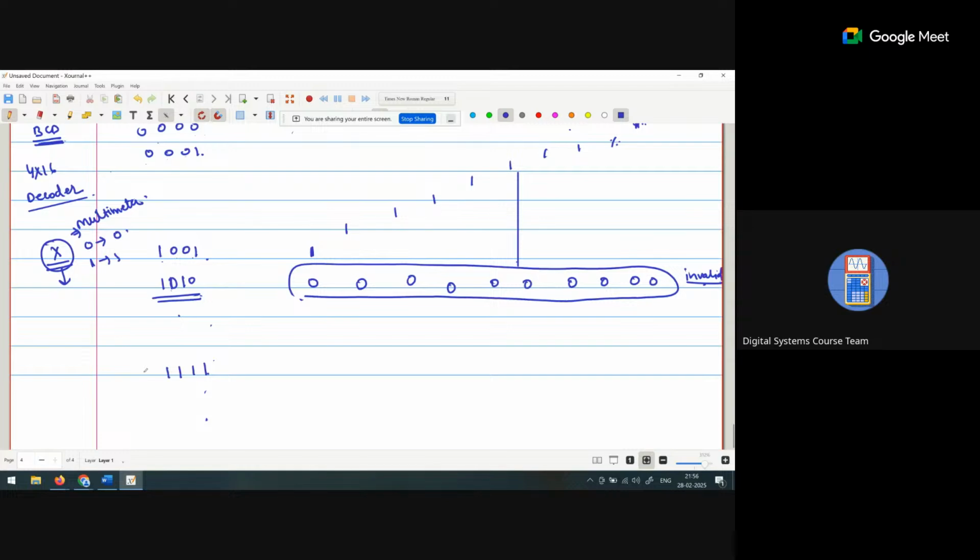You check 1 by applying and checking the voltage, 5 volt. But how do you check the x don't care condition in the multimeter? Is it possible? Not possible. No. Okay, so in the written part it is automatic. If I say that in the written part it is the invalid state, but in the decoder, if you apply from 0 to 9, any one of the outputs will be 1. But if no output is 1, it is automatically defined as an invalid state.